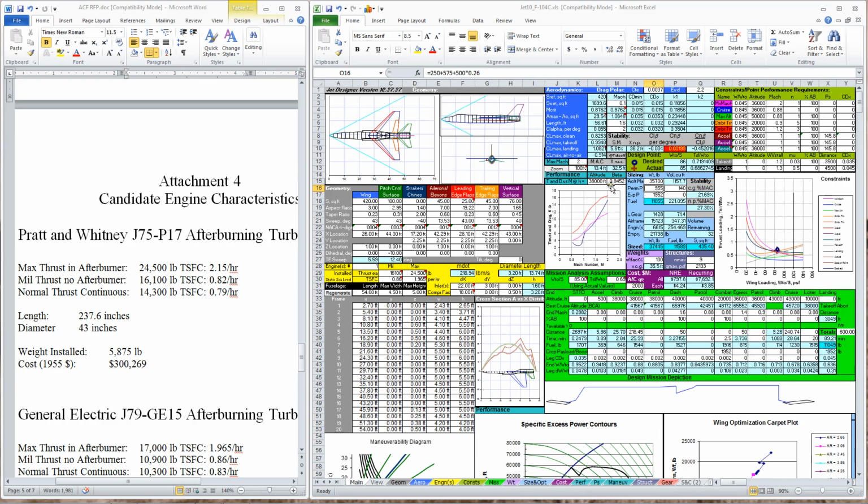Well, that's a nice looking airplane. One of the things, it looks like we need just a little bit more on the vertical tail. 35,737 for the takeoff gross weight. Airplane closes. All right. Now we have a good solution to the sizing equation. It's very close to our actual solution. We've got our plus very close to the circle.